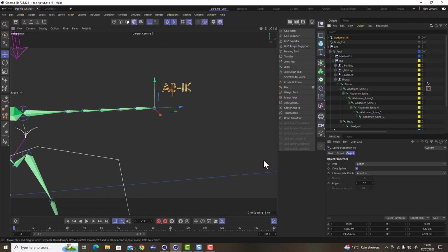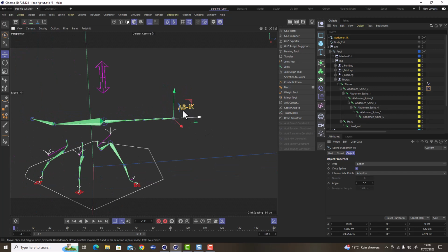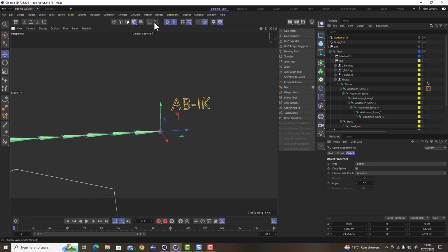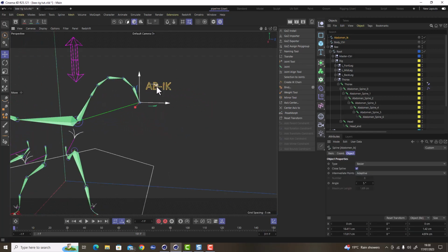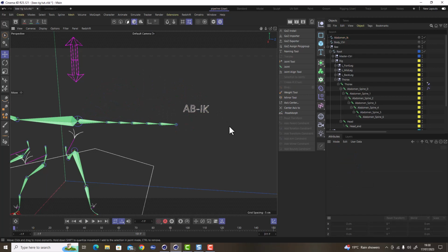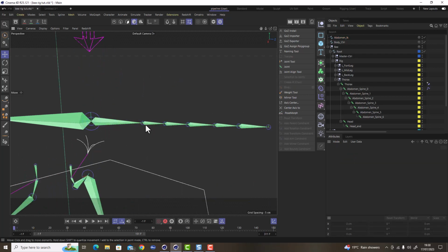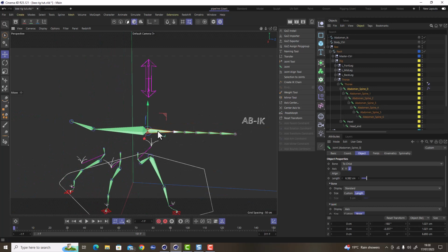And also you do have the ability to make sure that when it comes to certain other constraints, you can actually do the offset trick, or use the offset feature, shall I say, so it doesn't make everything move when you put something in there that's of a different orientation as a controller. But that's done now, so when we select this and we move this, we've now got that done for us. The other thing is I want to be able to grab this as a separate control and